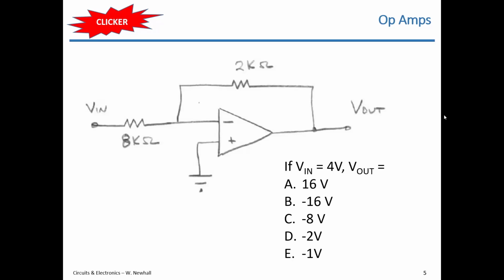So this is another one of those circuits where you should recognize it. First, we try to identify, does the circuit have negative feedback? I claim it does because there's some connection between the output and the inverting input where none of the nodes in between are held at a constant voltage. So this circuit has negative feedback.